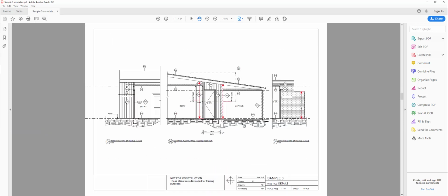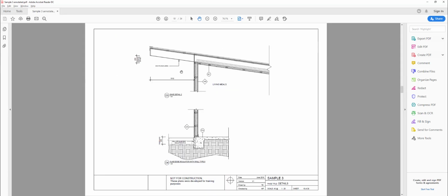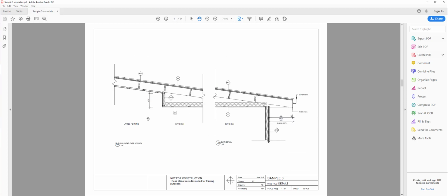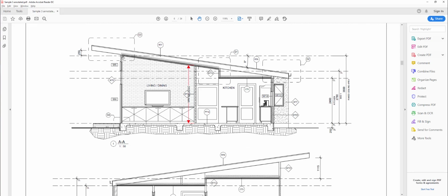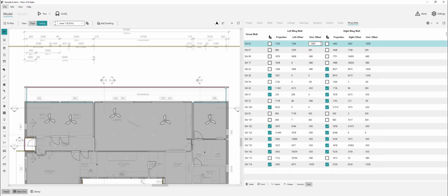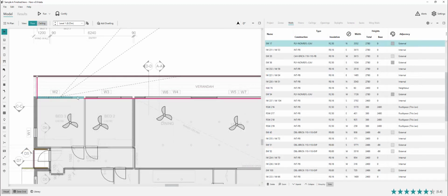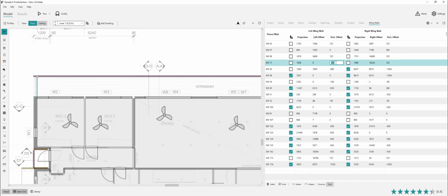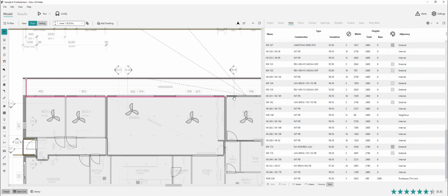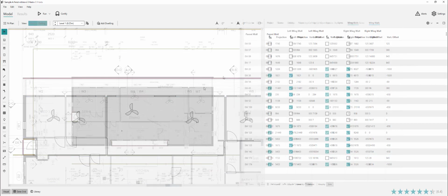These wing walls are going to be modeled, again, as a pitched setup, so we'd be modeling it as the average wall height for that wing wall that's poking out there, and we know that dimension is 3600 at its apex with a 250, so we'd be going 3600 plus 125 as the heights there. So we could just put 125 as our vertical offsets for the top of our wing walls. For our 2780 ceiling, our wing wall heights there will actually be the 3725 average height. Take the 2780, so 945 as their vertical offset. We'll step through the next ones.